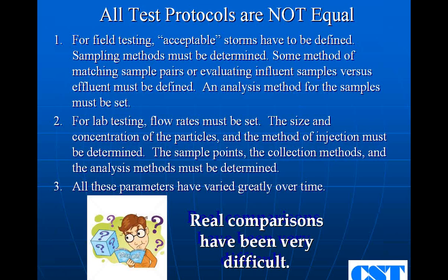Going back again to the ETV, one of the reasons I like it is because it has been consistent, and everybody, fortunately or unfortunately, got subjected to the exact same analysis method and the same samples. And then finally, you do have to decide, how are you going to analyze these samples? TSS, SSC, turbidity. If you're looking for solids, there's standards for testing. For phosphorus, whether you want to look at total P or dissolved phosphorus or particulate. So there's a lot to how these test protocols are written.